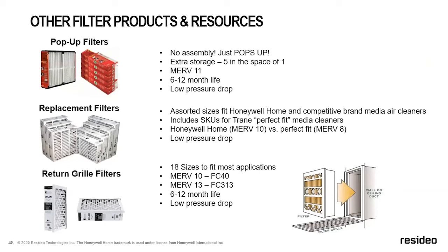The benefit there is for a maintenance or demand response technician that's doing filter changes and things while they're on site. You could store up to 5 of these pop-up filters in the place of one filter that's already in place. So if you look at the replacement filters up below, when condensed down as a pop-up, you can fit 5 in the place of one. 6 to 12 month life, low pressure drop, and it's also MERV 11.